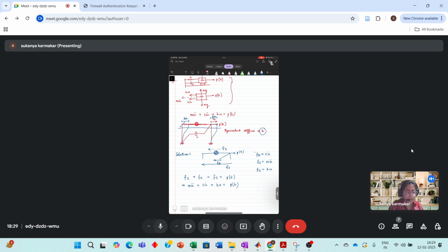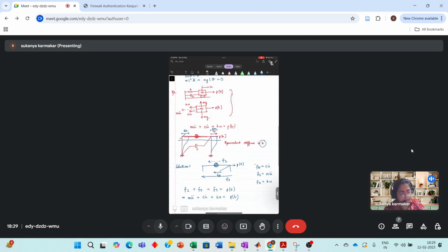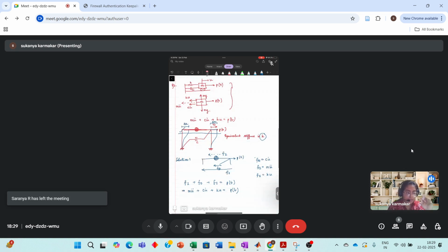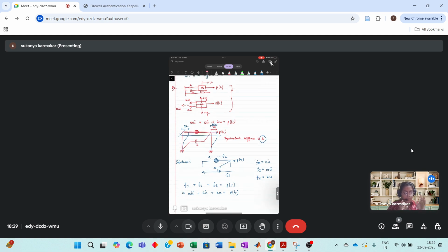The systems look different. This system, the mass spring dashpot system, and the system where you have a portal frame, with certain assumptions that the entire mass is lumped at a point in the slab. Let's say here it's lumped at one point. The beam is rigid.